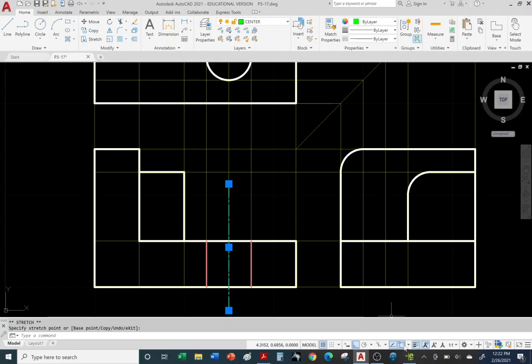Okay, so I'm going to turn off object snap so I can have freedom to move this endpoint. As you can see, it's not trying to snap to anything anymore. Okay, so there it is, and hit escape, and there's the axis of that circular hole. Okay, so once again, we were not able to see it from the front view, but we need to represent it with the green center line and the red hidden lines. All right, so I think we're done with the front view.